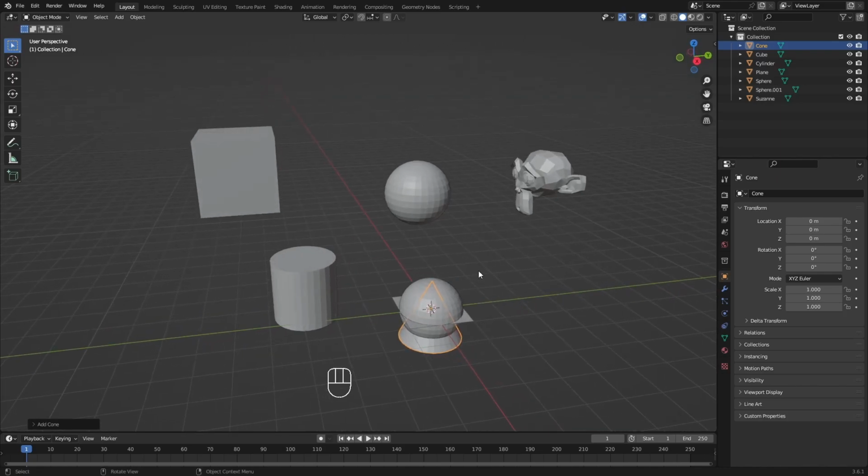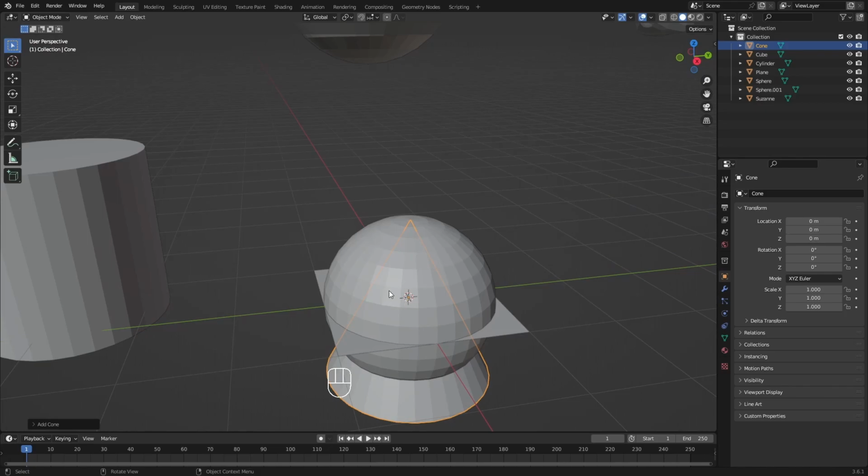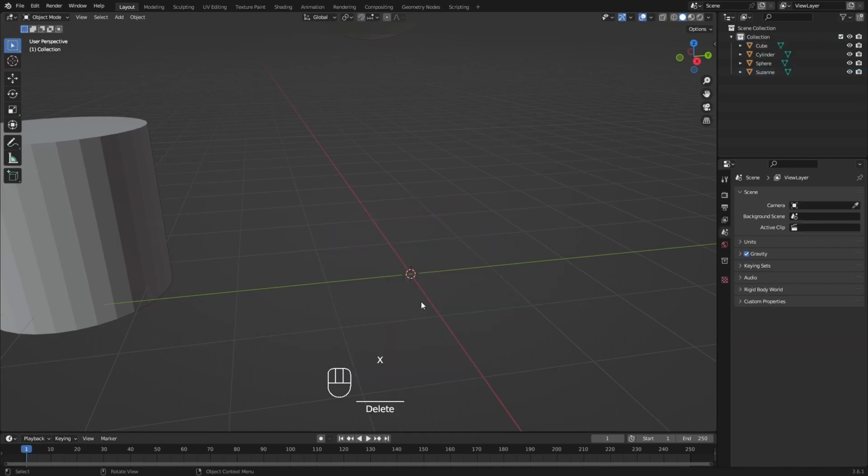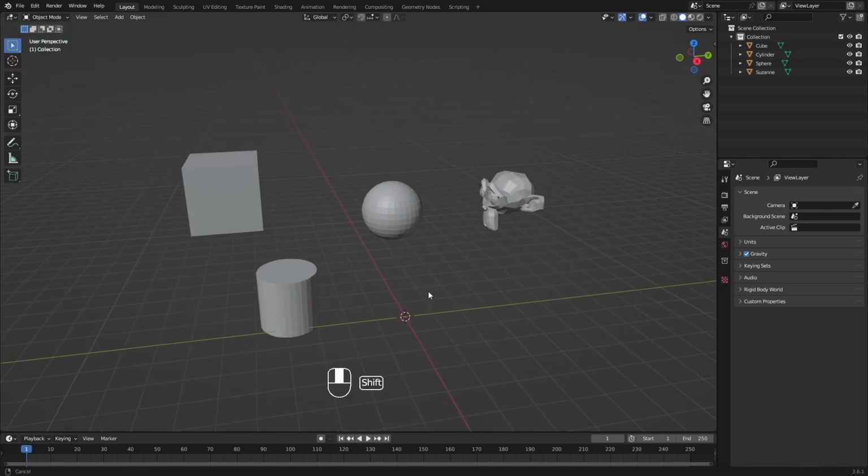And for example, here we have this little thing like a dashed line with red and white. Let me actually grab these guys here and delete them, so it's easier to see. Okay, so we have this dashed line, red and white thing. This here is the 3D cursor. And the new models are going to be placed exactly where this guy is.